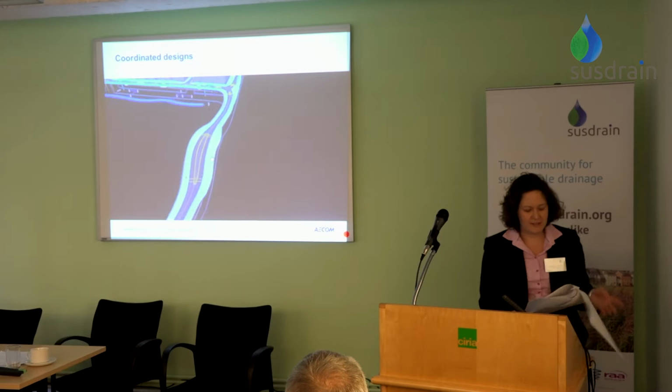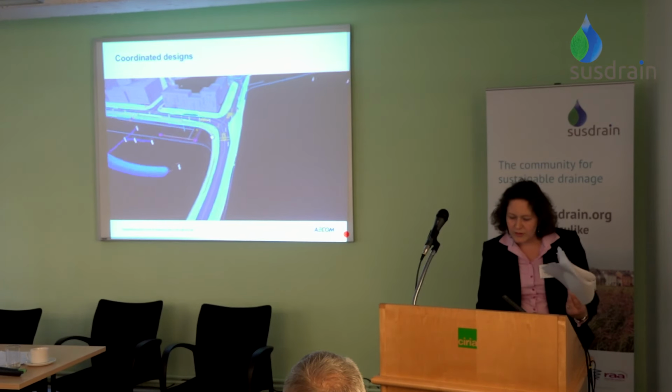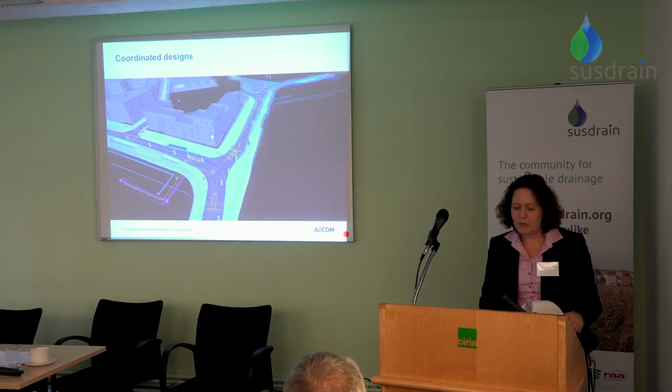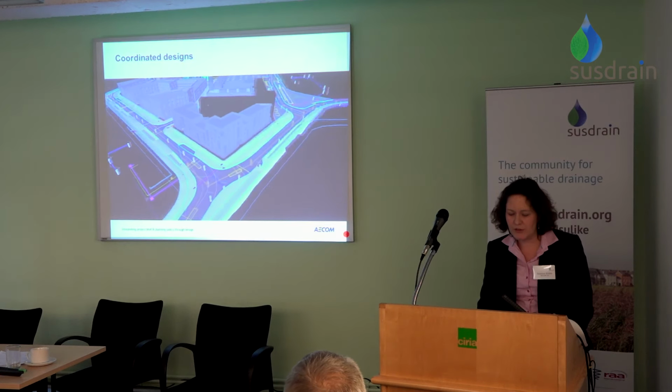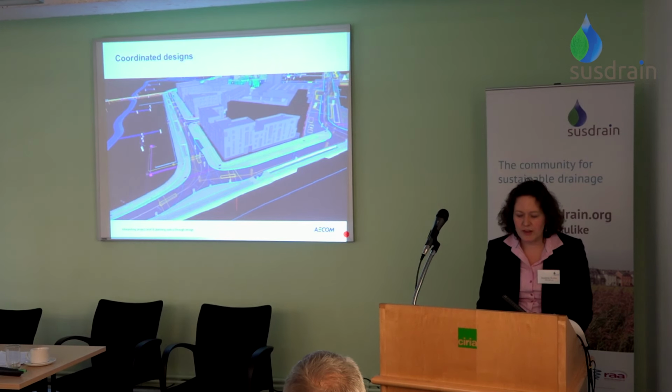Will it work? Okay, so here's my fly through. What we're following here is the primary street running through the development. If I try and pause it, we have one of the key green corridors running on part of the site here which will outfall to the western edge. We also have depressions that we've modelled for the swales, and these are some of the hard standings where we'll have bin locations. We also have the foul network in brown and the surface network in blue.